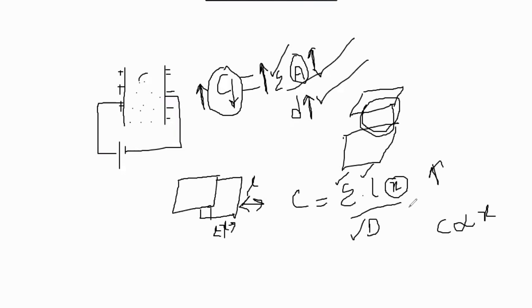Right. So now what can we write here? Suppose we want to find the sensitivity. How do we find the sensitivity for the overlapping area? You have already solved this problem in the last class. Sensitivity means the change in output by the change in input. Here the output is the capacitance C, that is dC, and the input is X, the overlapping area. X is the changing input.